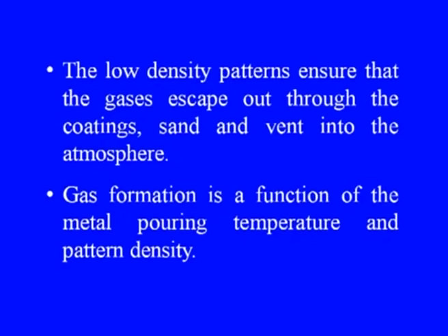Pattern density and bead size. Density and bead size play important role in evaporative pattern casting process. In order to minimize the amount of gases evolved during evaporation of the pattern, patterns with low density are generally used. The low density patterns ensure that the gases escape out through the coatings, sand, and vent into the atmosphere.